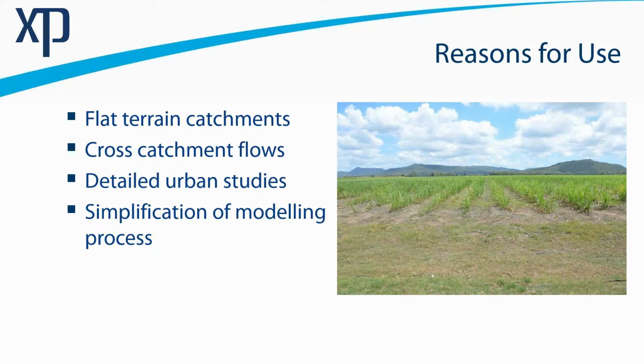Now, where would you apply this method? Well, it's very, very attractive where you have very flat terrain, because often it's very hard to delineate where your sub-boundaries are for your catchment or hydrological modelling. And so it really makes that process easy, you don't have to decide anything, you just let the modelling decide for you. And Gavin will be showing a nice example at the end that demonstrates that.